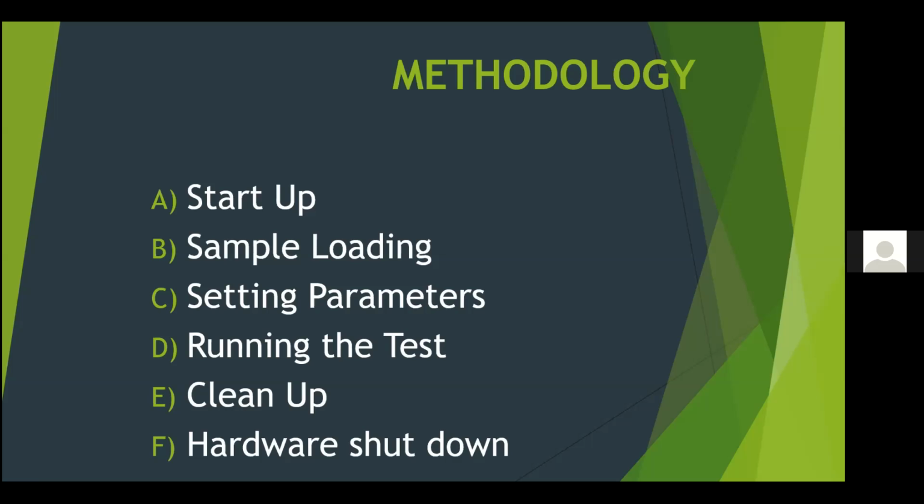The software, TA Universal Analysis, was opened on the desktop of the computer. The calorimeter was started by pressing On in the control tab. Then, scrolling down to Event, Go to Standby Temp was pressed. This was to make sure that the cell did not freeze.